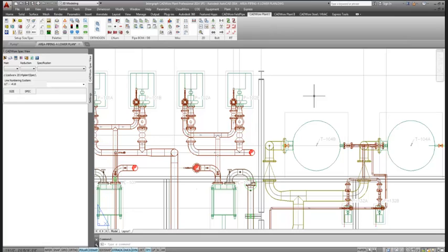So it's going to be a big plus for those of you that want to create orthographic drawings automatically. This will create your orthographic drawings automatically based off of any named views that you have on your sheet. You can also use those automatic AutoCAD projections inside AutoCAD to create your projections automatically, and then use Orthogen to create your annotations.